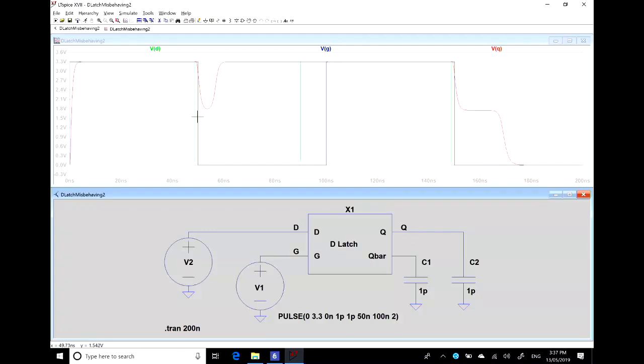But then you slam shut the gate, and the capacitor ends up stuck, not quite at halfway, but just above halfway. And those two inverters in a loop will push you back up to a 1. And so it goes back up to the 1 here, and that's what you get there. Whereas down here, I've got it just the other way. It's just long enough so that you shut the gate, the capacitor's discharged to just under halfway probably. It gets stuck at pretty much halfway for a fair bit of time, and then it falls back down to 0.